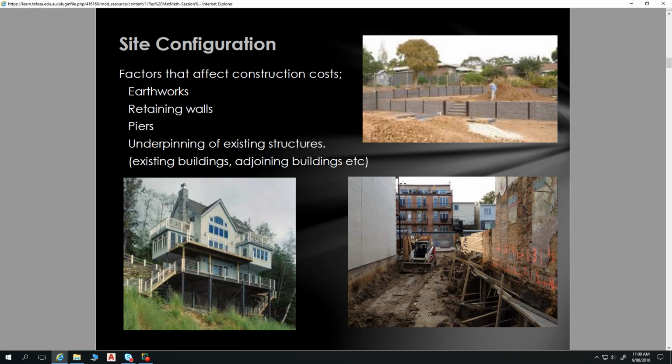And when I used to work doing the repair and reinstatement stuff, yes, we get these tiny little earthquakes in South Australia. We haven't had any significant disaster or any significant earthquake. But following on from that, you get a flurry of jobs that come in for earthquake damage, and a great contributor to that are pre-existing conditions. So where you've got soil which has subsided or shrunk, or soil which is lifted up, putting stresses on a building, and then you get a little bit of movement.